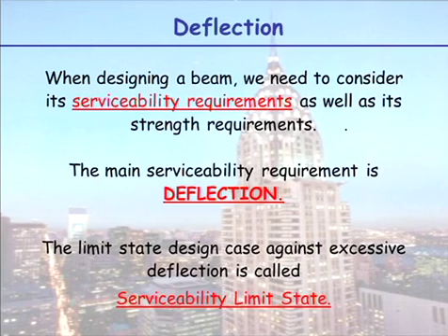when we design a beam or any structure, we have to consider serviceability requirements as well as strength requirements, and the main serviceability requirement is deflection. What are the other serviceability requirements, you may be asking? One would be vibration, if you're building a sports floor.